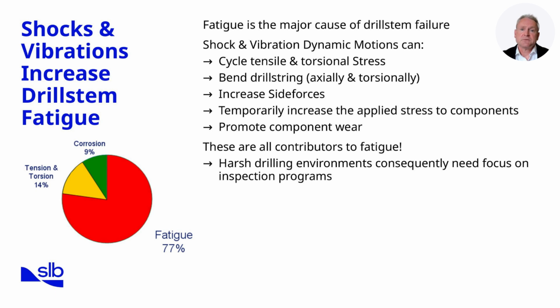At the same time, short bursts of vibration temporarily increase applied stresses on connections and components, pushing them closer to their fatigue limit. Wear is another outcome. When shocks occur, components such as stabilizers, jars, and drill collars experience accelerated surface damage. This reduces service life and raises the chance of catastrophic failure.